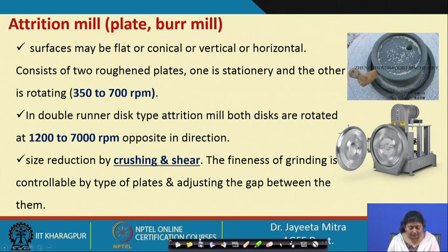Size reduction is by crushing and shear, and the fineness of grinding is controlled by the type of plates and also by adjusting the gap between these two plates.